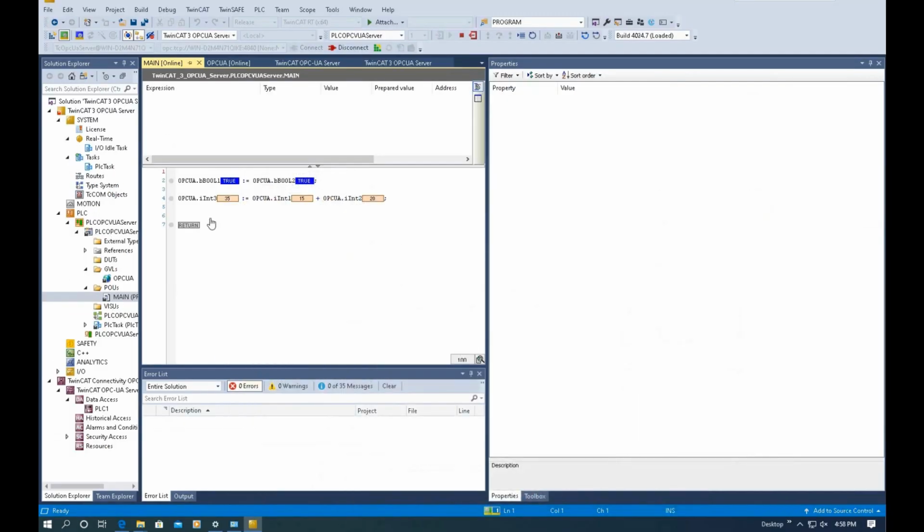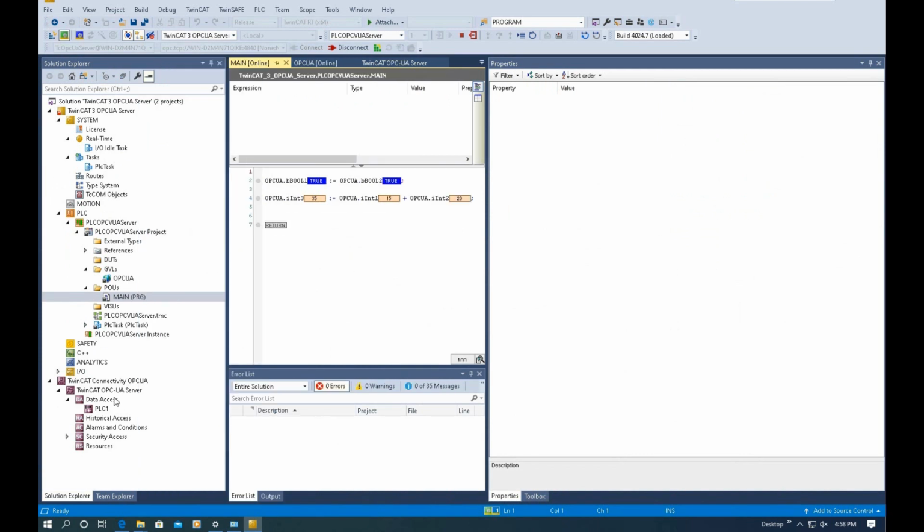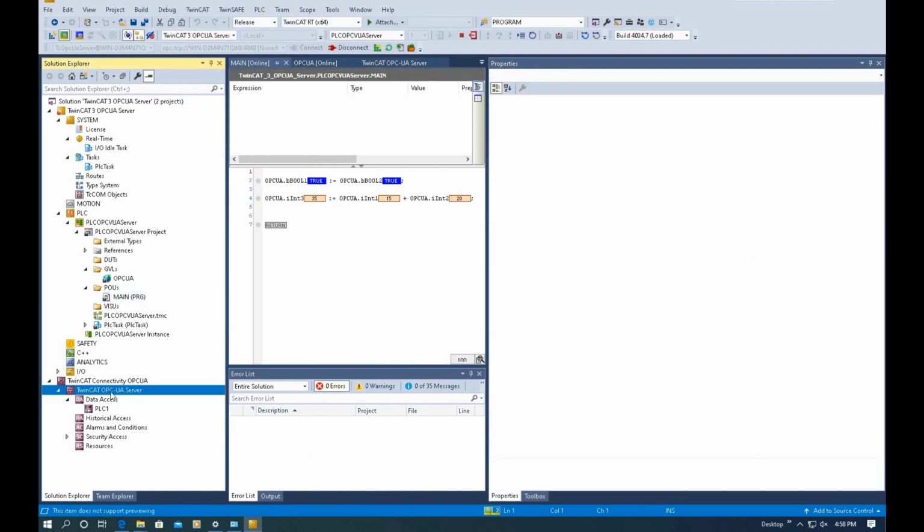So that is everything. If we recall the key settings around here, this connectivity and especially this UA server, as well as at the top, this area, these are the key settings for the OPC UA server setting. From this column, we set up the OPC UA address, and in this column, we select the actual security settings. And once we hit this connect, keep in mind it will pop up the anonymous settings. And eventually we need to hit this active OPC UA server config. And sometimes if it doesn't work, you can try to restart the OPC UA, and keep in mind the PLC must also be running.